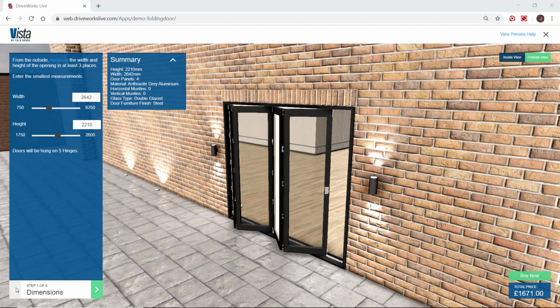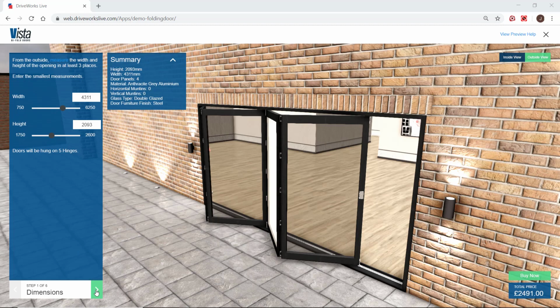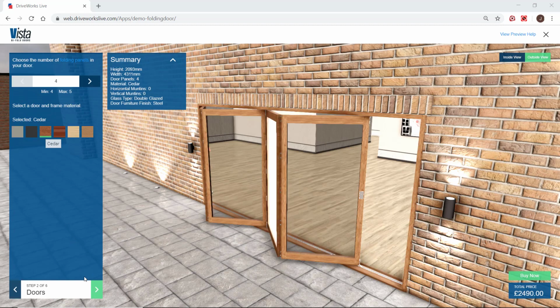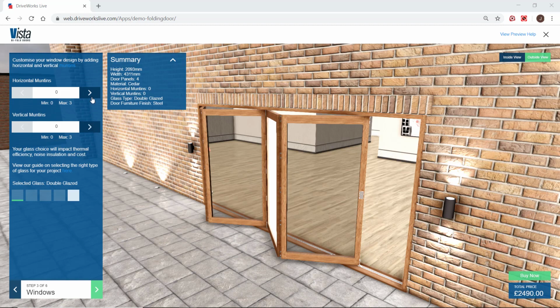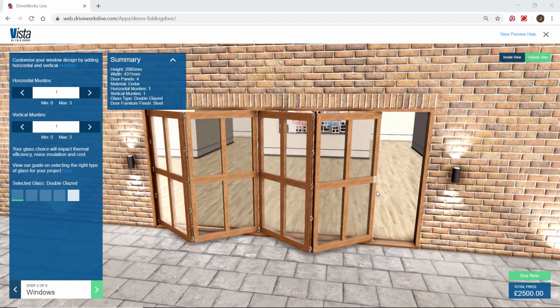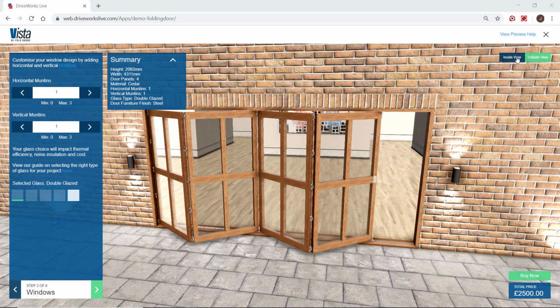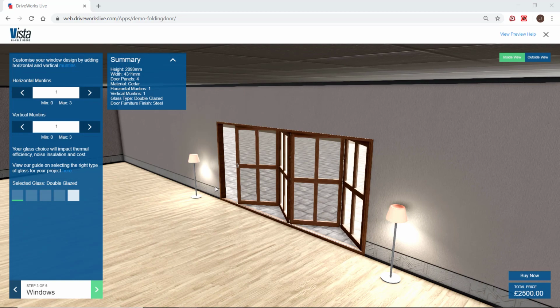Lastly, with DriveWorks Pro, we can generate 3D previews. As I fill out my form controls on the left, you can see 3D data in front of me changes in real time. Not only will the 3D preview allow us to reflect changes in dimensional data, but we can also swap out appearance data such as textures and bump maps, as well as allow us to control lighting elements in the scene. But if you really want, you can also let the user interact with your 3D. I can rotate the scene around, and I can interact with the model itself. And in this case, there's a macro button that allows me to do all of this again from another vantage point altogether.